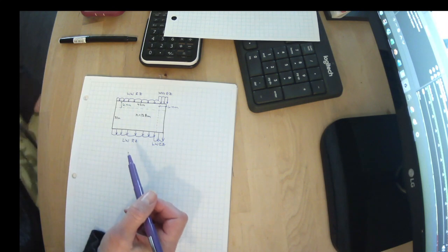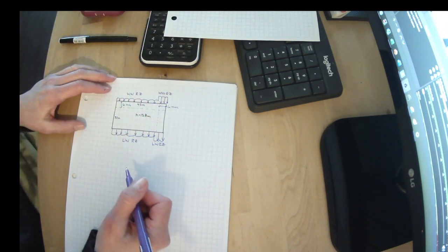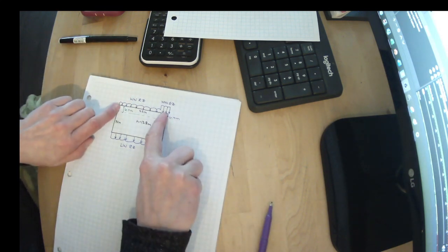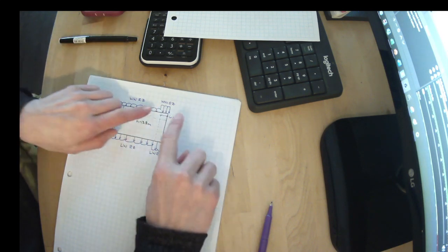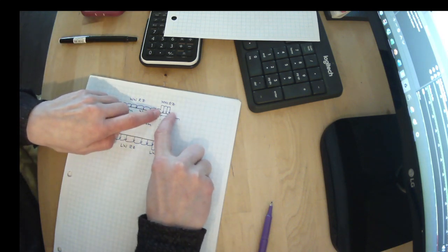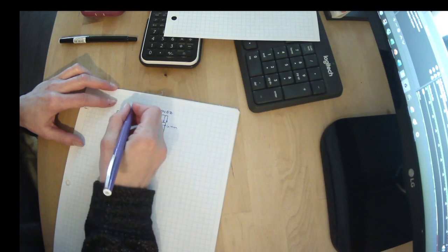And we've calculated these. All we need to do now is figure out the area, or the surface area, that these are blowing on. So the windward regular side is blowing on this distance times the height. The windward end zone is blowing on this distance times the height. And we've calculated what these values are.